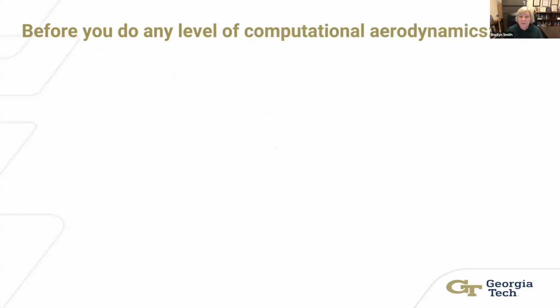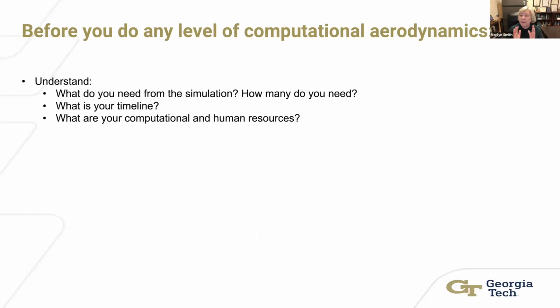Now, before you do any level of computational aerodynamics, please, please, please take this in mind. Understand, what do you need from the simulation? How many simulations do you need? What's your timeline? And then what are your computational resources? Do you have high performance computing from somewhere, or do you have a local cluster, or maybe even just a PC? What are your human resources? How many people can work on this? Choose the best tool and approach. Don't go just because somebody says, oh, we're doing this. Hey, you can get great results without having a ton of resources. Trust me, you can.